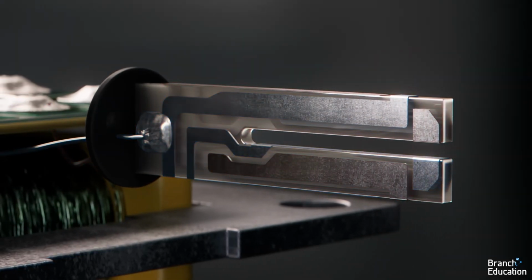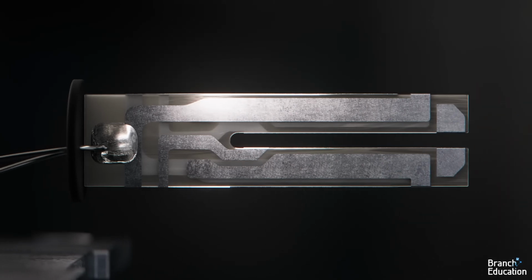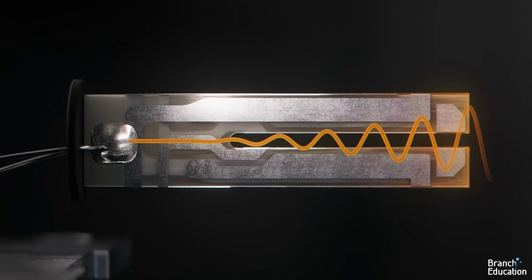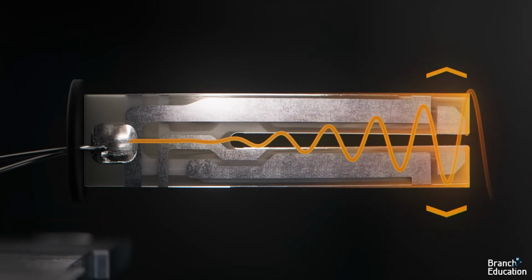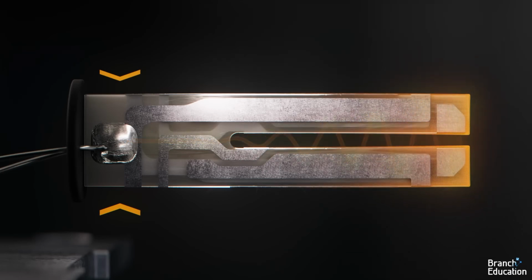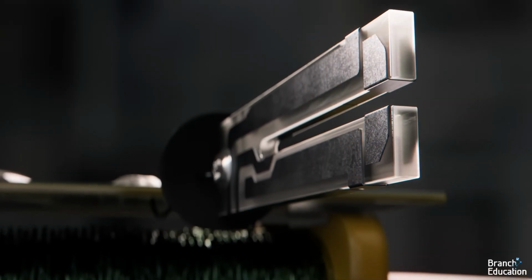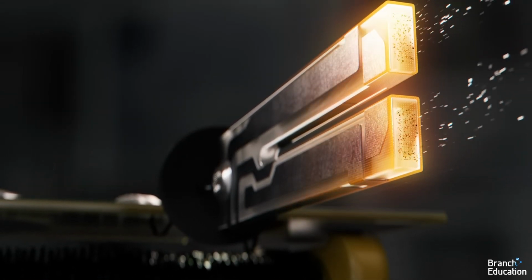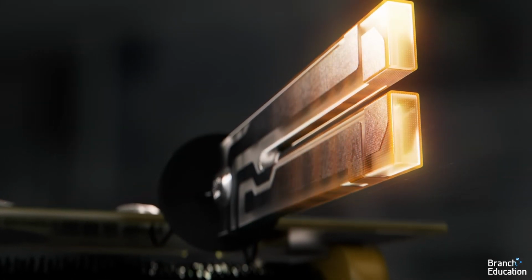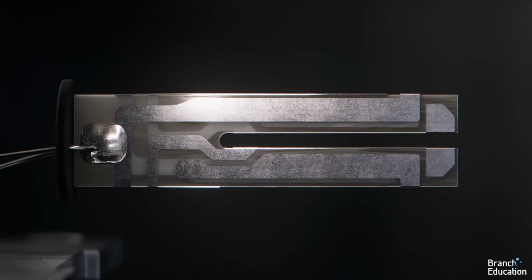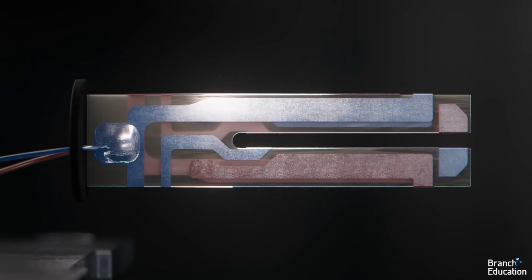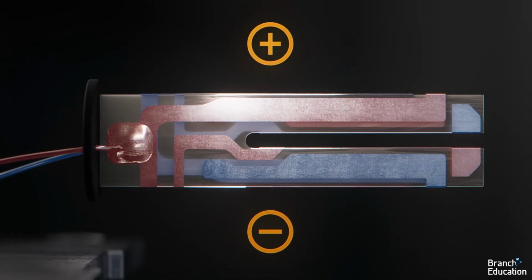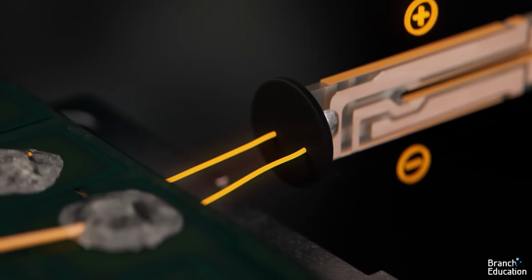The purpose of having two legs is to create a vibrational mode wherein the prongs vibrate and resonate together while the base doesn't move. Frequently, manufacturers add small amounts of metal to the ends of the crystal to tune it to the desired frequency. However, to get a crystal to continuously oscillate, a changing voltage needs to be repeatedly applied to the wires on the legs.